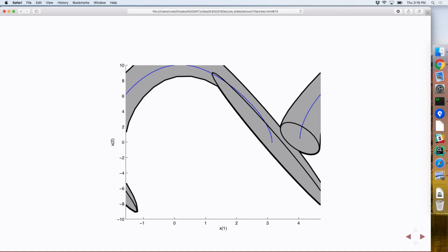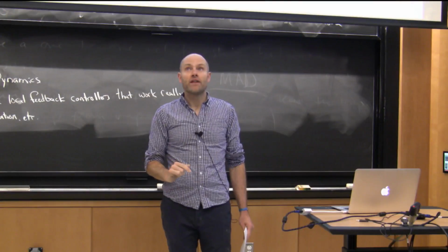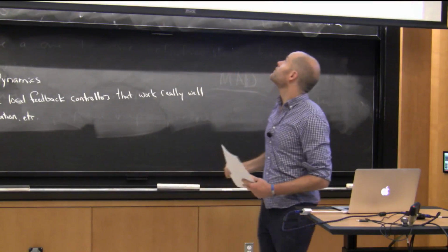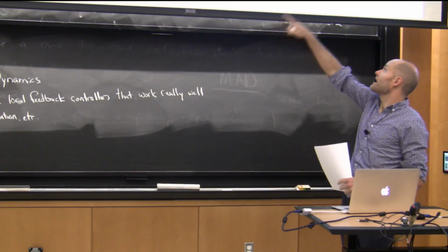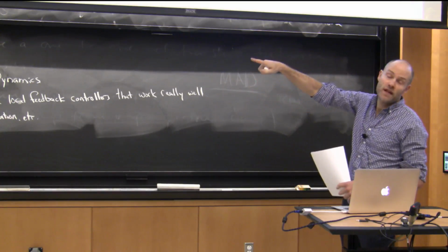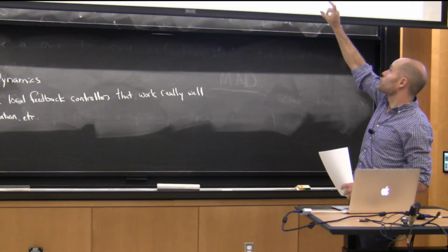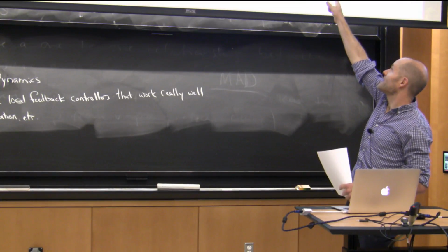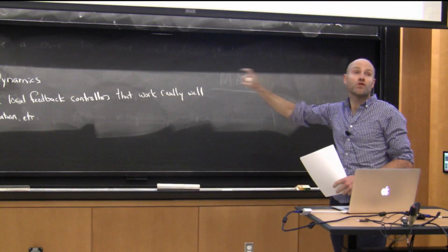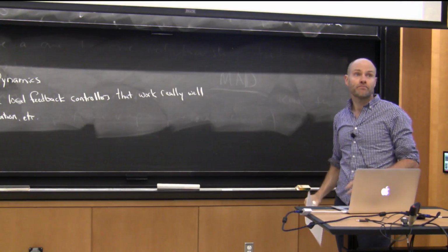No. That's very tempting, but the requirement is actually that you end up back at some node in the tree. So there's a skeleton inside the funnels, and the specific requirement is you end up at one of the nodes inside there. That's for a number of reasons, but the simplest one is continuity, of having an infinite horizon trajectory, but you also want the controllers to lead into each other. If you ended up right at the edge, you wouldn't know how to have a smooth controller along the transition.